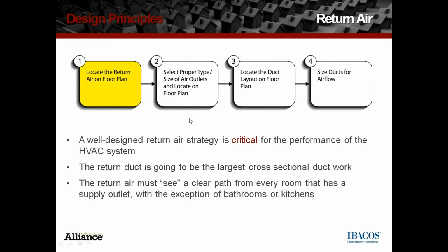Return air is very important. We at IBACOS, and I think in general, look at the return air first. Maybe a little bit pragmatically, because return air is often neglected, but it is a critical component. Your return air is going to be your largest cross-sectional section of ductwork. It's going to be the biggest piece in the house. You have to think about where that's going to be relative to the rooms to get good return.